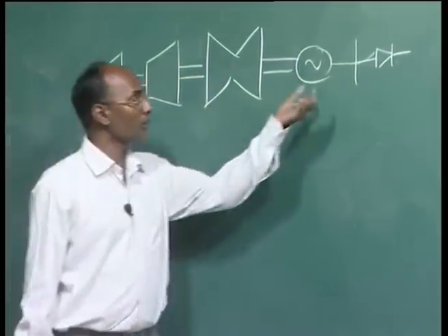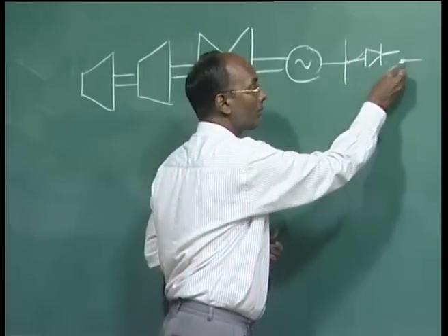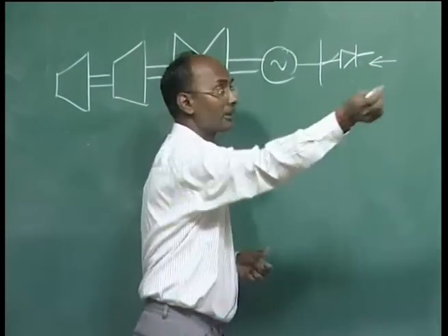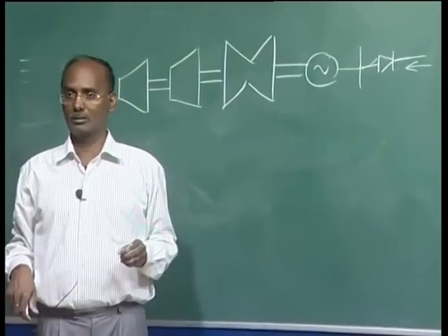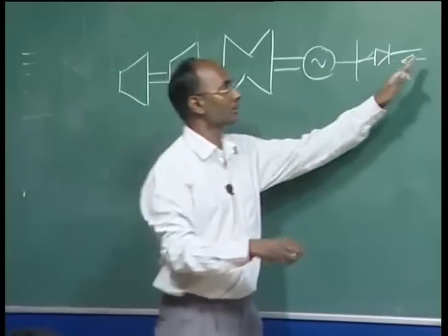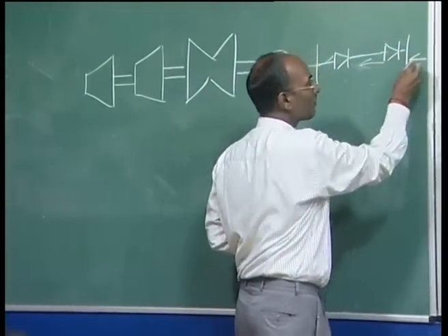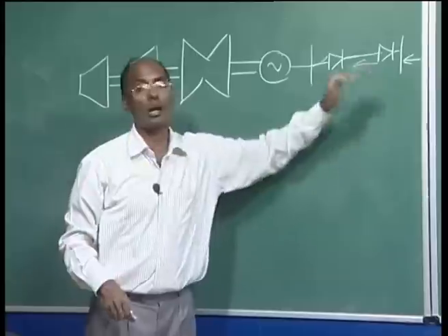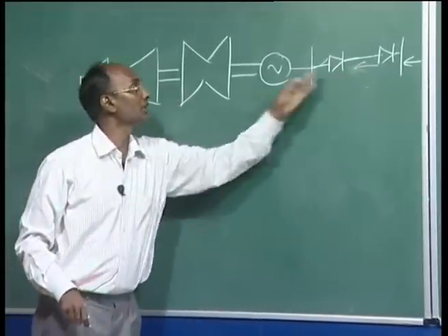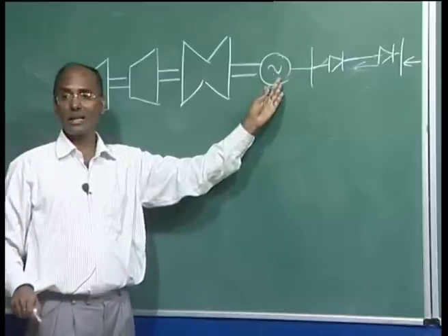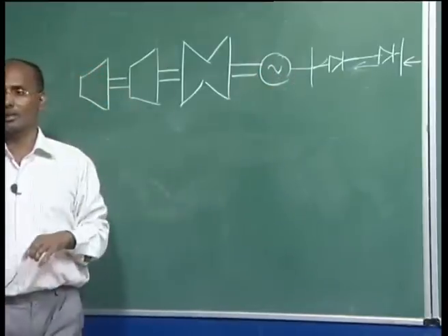What happens if you put this one here? If a frequency is entering here from another area, it will not go inside because of the DC. Here, of course, you have an inverter, so if some frequency in the system is entering, it will block here. So it will control, sometimes, that the current harmonics do not go into the generator winding, and therefore there will be no SSR problem.